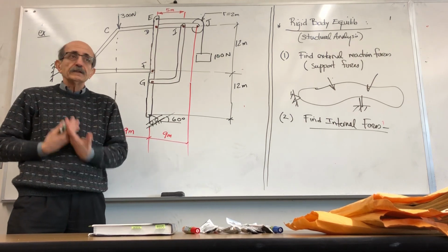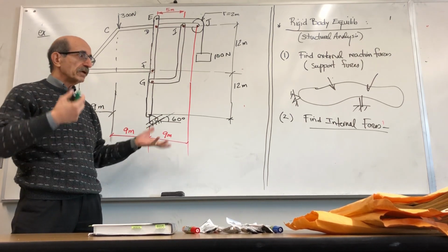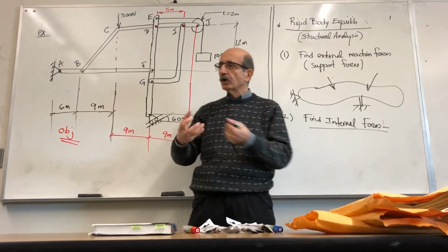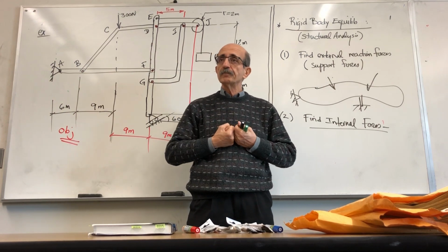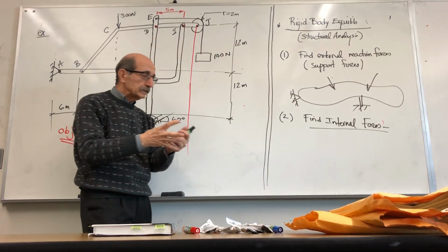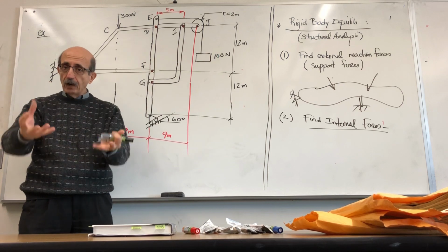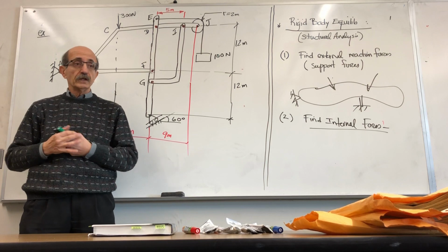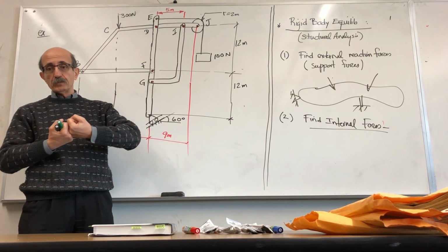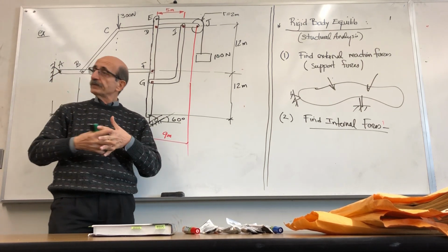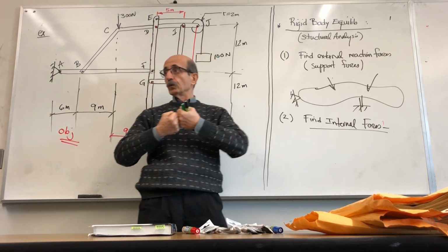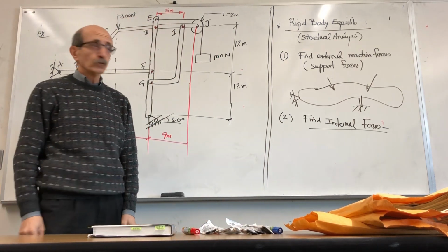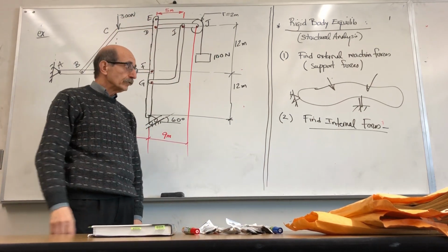These pieces are connected together through bolts, maybe welded, or riveted. There are all kinds of mechanisms that hold these together. When you want to design a structure like that, you need to know what kind of forces each component is subjected to. The reason is that those connections, whether bolts or welds, carry some load which is holding these two pieces together. We want to find out what those forces are so that we can choose the right bolts, for instance.